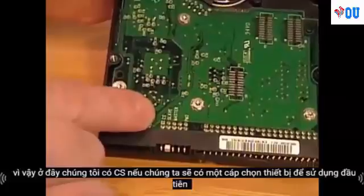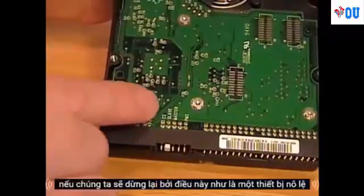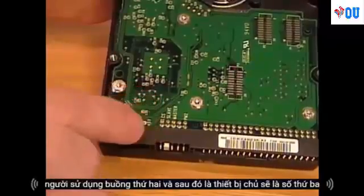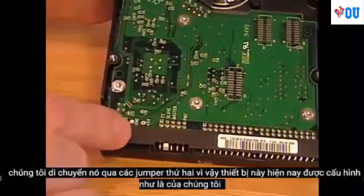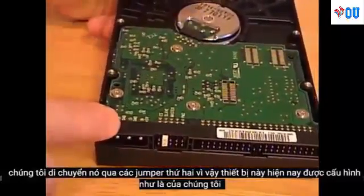So here we have CS. If we were going to have a cable select device, we would use the first jumper. If we were going to specify this as a slave device, we would use the second jumper, and then the master device would be the third jumper. In this case, this is going to be our slave device. We will move it over to the second jumper. So this device is now configured as our slave device.